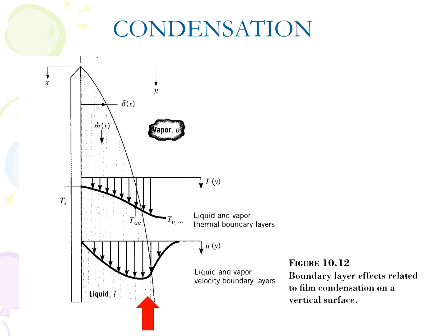At the surface of the liquid film on the vapor side, the temperature is Tsat, because this is where condensation takes place. The temperature then decreases as the cooling surface is approached. At this surface, the temperature is maintained at Ts by the heat sink. The velocity profile is also given, with both vapor and liquid moving at the liquid-vapor interface, and the velocity of liquid at the vertical surface being 0.